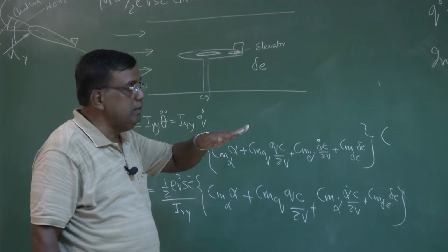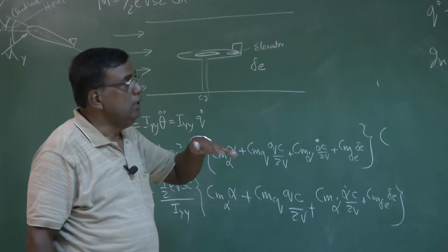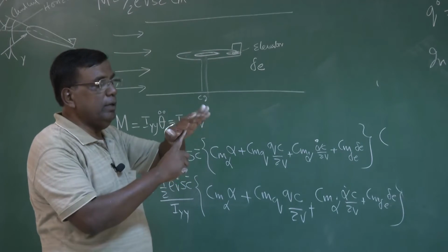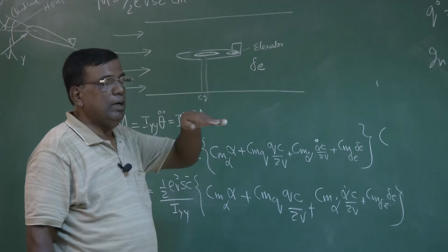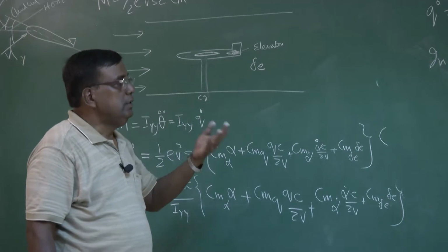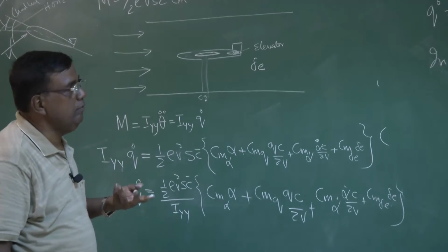In a tunnel, in actual practice, what will happen for an airplane? If there is a disturbance, it will not only do this, but also will change the height because there is a lift force. Allowed to move. But here, because it is having only 1 degree of freedom, it can only do this. So the velocity vector, the gamma flight path angle, remains constant. So theta equal to alpha, theta dot equal to q equal to alpha dot, and theta double dot equal to q dot equal to alpha double dot.